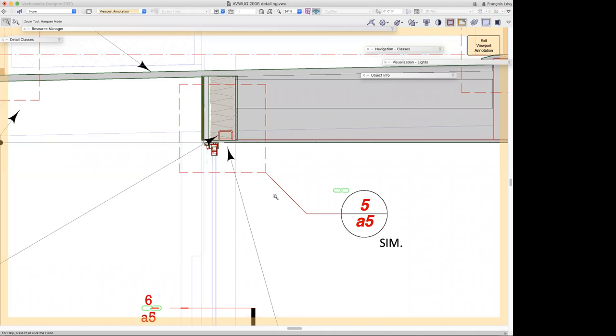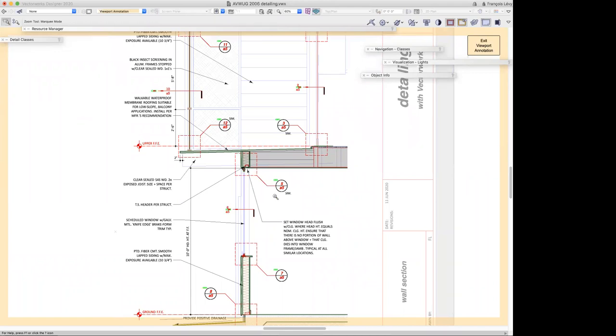So one of the reasons that we don't have super detailed windows and doors is because you only need to draw a window detail in a couple of instances: head detail, jamb detail, sill, and so forth. But if you've got 50 windows in the model, now you're carrying 50 windows with a super high level of detail just for the sake of generating 1 or 3 details out of that. So in terms of computational efficiency, it makes sense to not expect your model to be detailed at, say, 3 inches equals a foot, or in BIM parlance like LOD 500. We're not going to put in every piece of flashing in the BIM model because you're only going to see it a few times, and you can do that in the two-dimensional drawing.